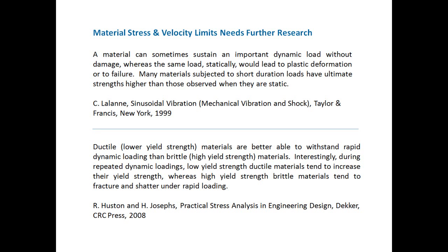And here's just a couple of quotes. I'll just read these to you, and you can kind of draw your own conclusions. A material can sometimes sustain an important dynamic load without damage, whereas the same load statically would lead to plastic deformation or to failure. Many materials subjected to short duration loads have ultimate strengths higher than those observed when they are static. And that's from C. Lalane, or Lalani, however he pronounces his name.